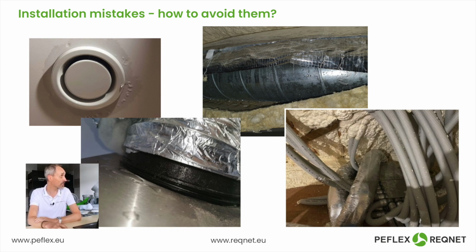We've already talked today about insulation, and the question is, is regular tape enough? No, it's not enough. It will give way. And when the tape gives way, air will get into the pipe, water will condense from the air, and again, it will start leaking.